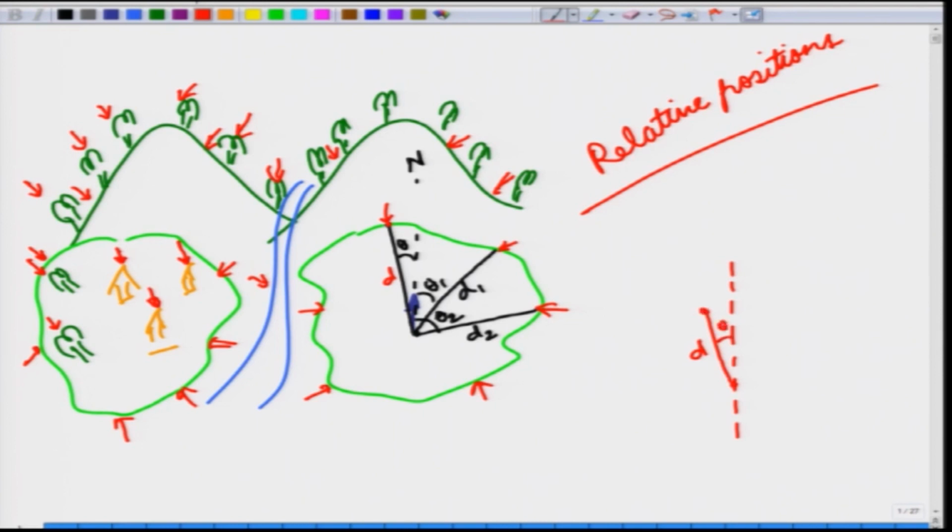So, you are marking the location of this point. Now, in this case you will make use of a scale. So, in this case your d on paper is equal to, or you will say that 1 centimeter on paper is say 10 meters on ground.